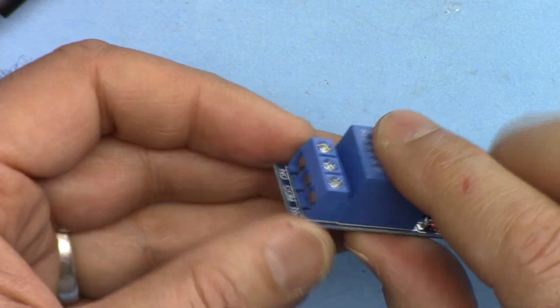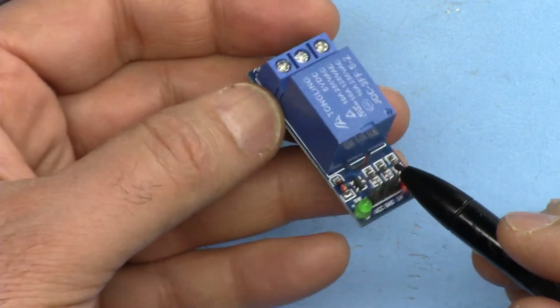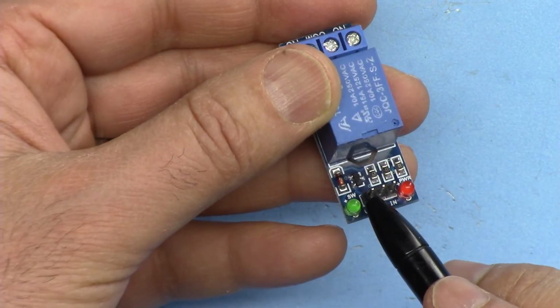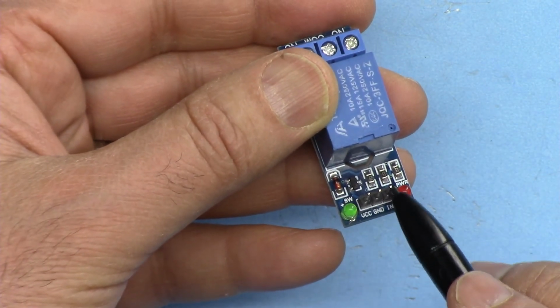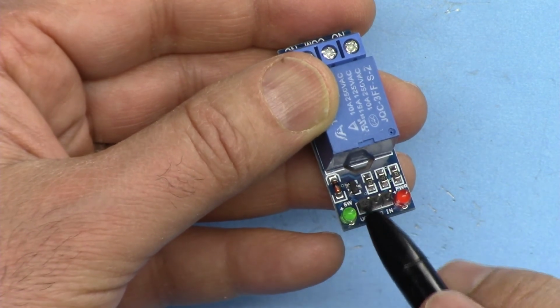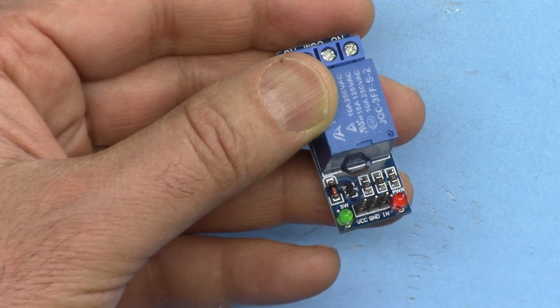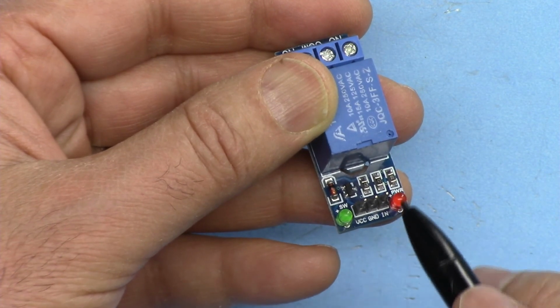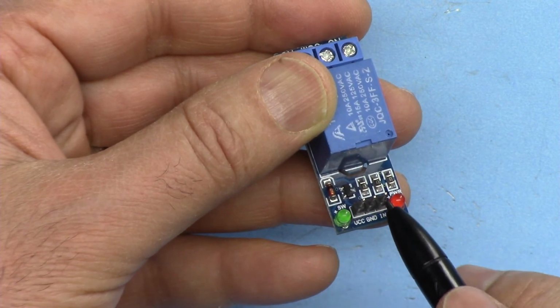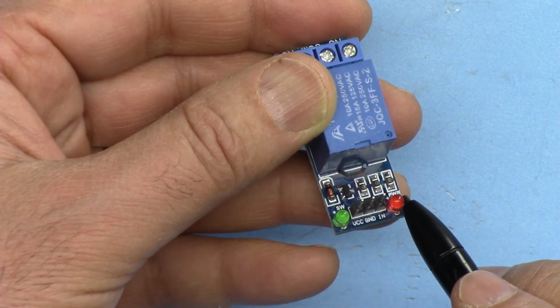Create a contact or turn on and off a load. It has 3 pins here. VCC will be connected to 5 volts. IN will be connected to the signal. GND or ground will be connected to the ground of Arduino, and this will be connected to pin 2 where we send the signal to this. This red LED will turn on when this has